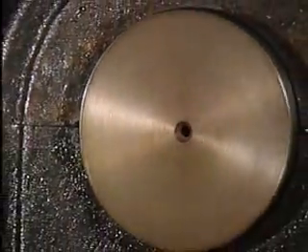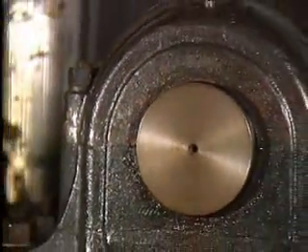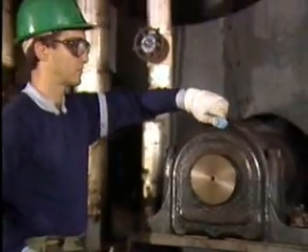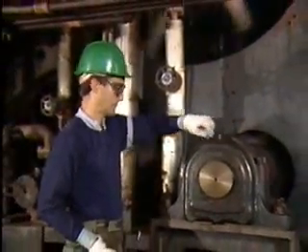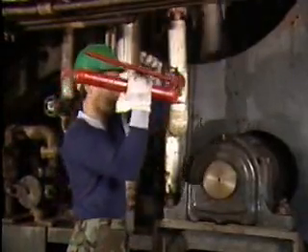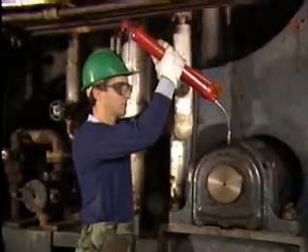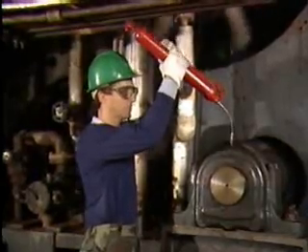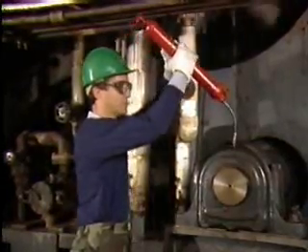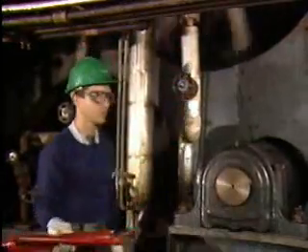distributed. If the housing doesn't have a drain plug, the excess grease or old grease leaves the bearing through the shaft seals. In this case, it is very important to add grease slowly to the housing so that the shaft seals are not damaged. A good rule of thumb is to pump the grease gun no more than 2 or 3 times unless specific plant guidelines state otherwise.